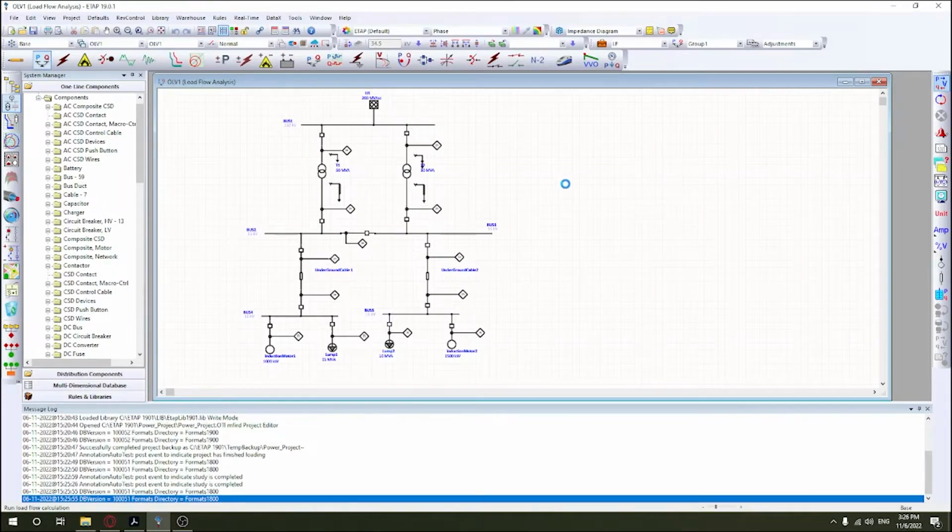Load flow analysis is necessary for making sure that each component runs at optimum operating point. As you can see here, for relay 1, the max load current is 61.9 ampere. Same goes to relay 2. Both relay 3 and 4 also have the same current, which is 743.3 ampere. The current values for each relay were tabulated in this table.